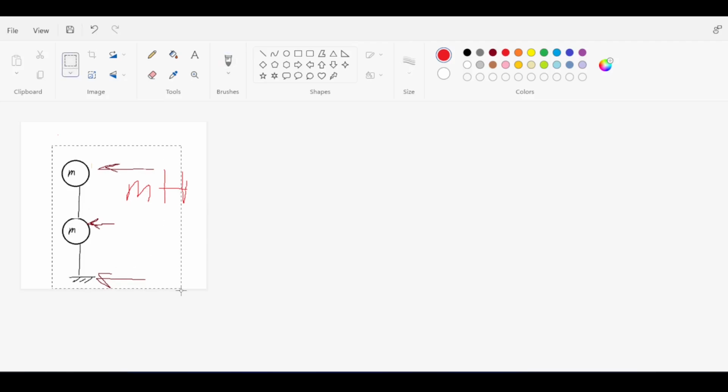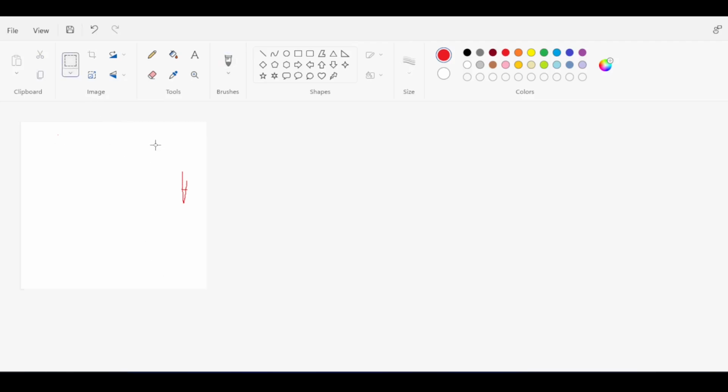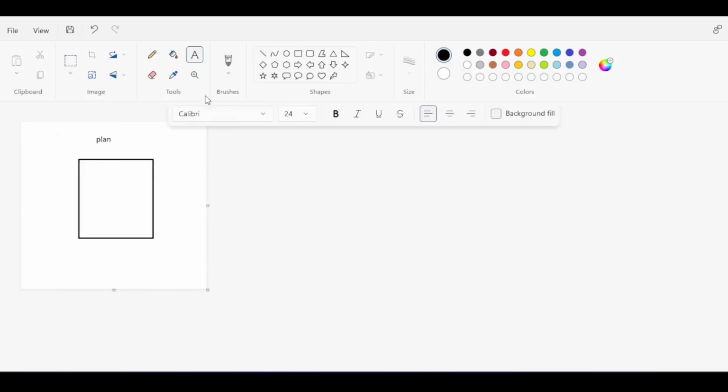Furthermore, the design codes usually, if I'm drawing a plan view now, assume that this is the plan view of your floor, the mass of that floor is in the center of gravity of the shape, which is basically the center here. Now, this is true for homogeneous shapes, but in reality, the center of mass is actually not the center of area, because the distribution of loads and weights on that slab is impossible to be uniform.